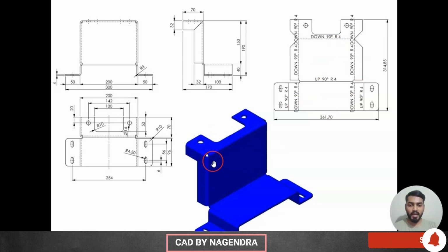After making all this design, if we flatten the sheet, then we need to get this particular design. In this shape only we are going to cut the material using a laser machine. So laser cutting will cut in this way. After cutting the material, later we can go for bending options. Now let's see how to design this part, and let me show you how to do the drawing also, and how to insert this unfolded view also.